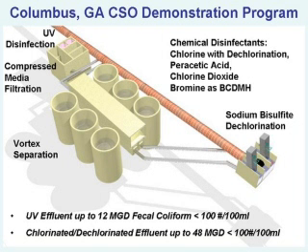In Columbus, as I mentioned before, we looked at sodium hypochlorite and sodium bisulfite for disinfection. We also looked at peracetic acid. There's a couple of vendors now that have this product. There's still some certifications that need to be done to make this a legal disinfectant for some of the various waste streams. I think for shipboard waste, peracetic acid is now a licensed disinfectant. I think in the state of Kentucky, they've licensed it for at least 1 year, and they're looking at various concentrations of that.